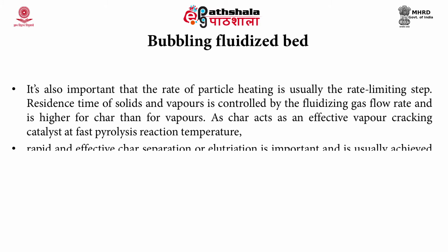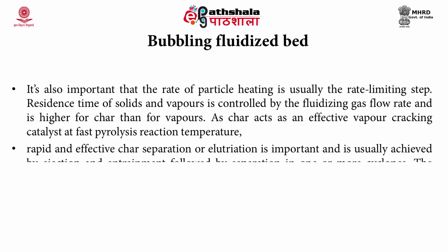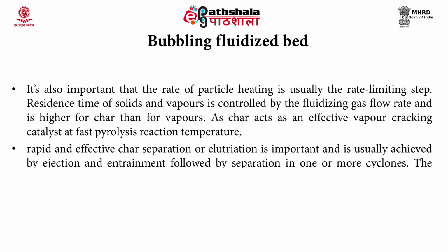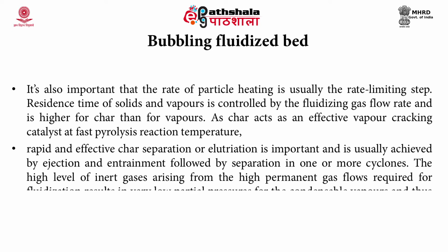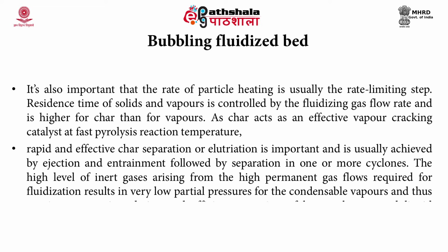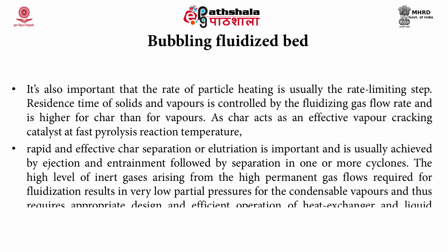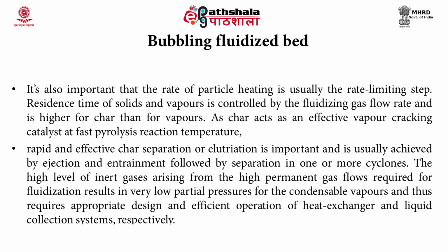separation and removal is important, and it is usually achieved by ejection and entrainment followed by separation in one or more cyclones. The high level of inert gases arising from the permanent gas flows required for fluidization results in very low partial pressure for the condensable vapor and thus requires appropriate design and efficient operation of the heat exchanger and liquid collection system in this type of reactor.